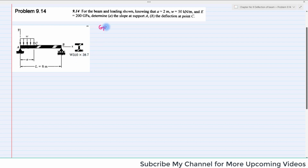So let's start with the given data. It is given that W310 by 38.7. Clear? Length of the beam is given as 6 meter. A is also given, which is equal to 2 meter. Uniformly distributed load w is equal to 50 kilonewton per meter. Modulus of elasticity E is given as 200 gigapascal. Clear?